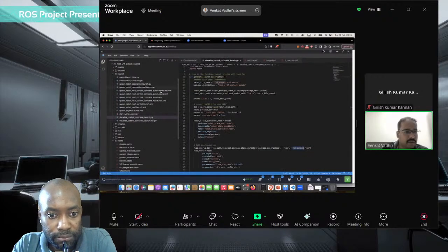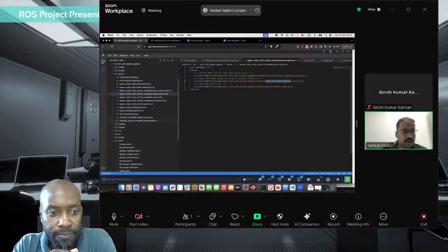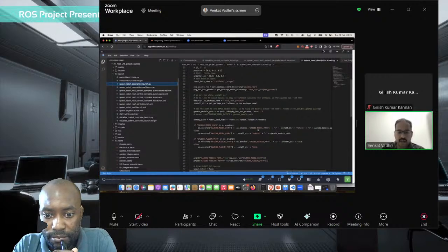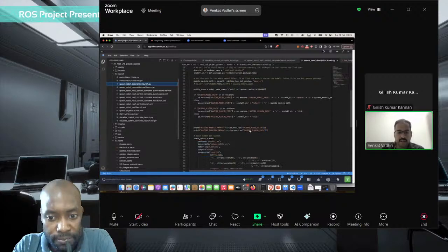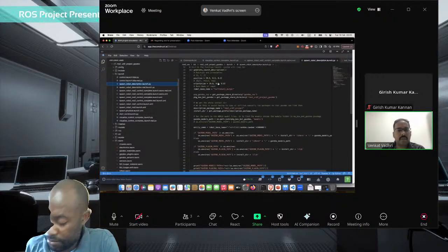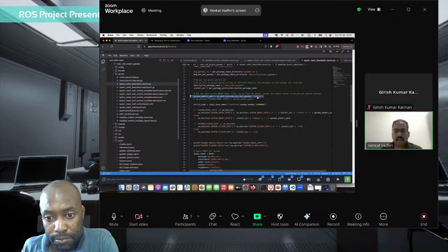If I go back to where we started, there was a visualize step, and then I spawned the robot, which is the robot description. Among other things, we add the Gazebo related model paths and plugins information. A critical thing is that inside the Gazebo simulator we position the robot in a specific place. We can give that using this spawning of the robot, setting a position and an orientation if we want. We also give various paths, telling where the model files are, where the environment and the plugins are, etc.